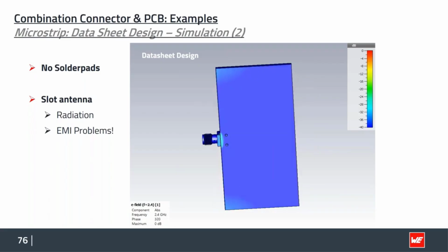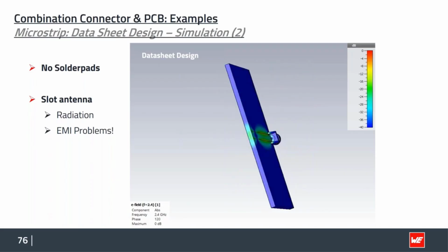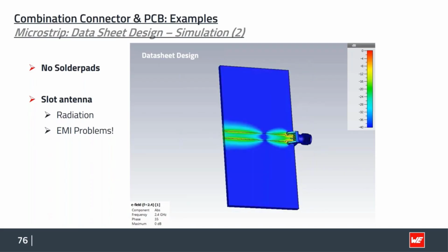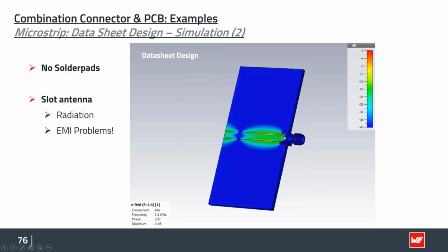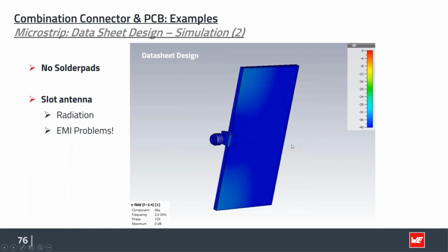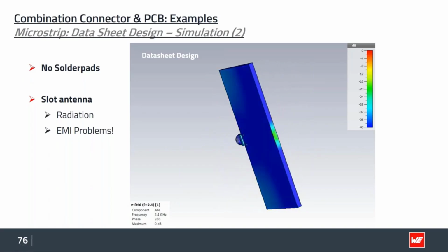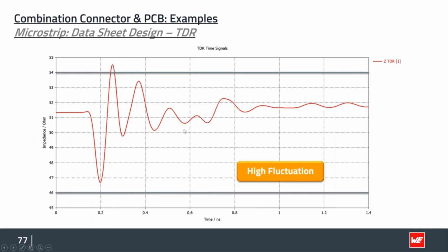And the other thing is that we do not really have a complete ground connection. We just have these 2 little pins that go on the PCB here as ground, but not in the first moment where it comes to the PCB. So the first thought we want to do is optimize ground, because I think we can do better than we can see here.